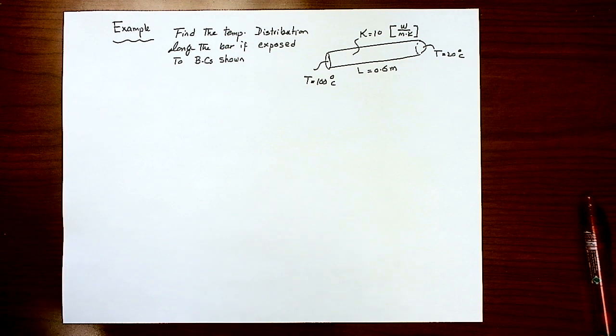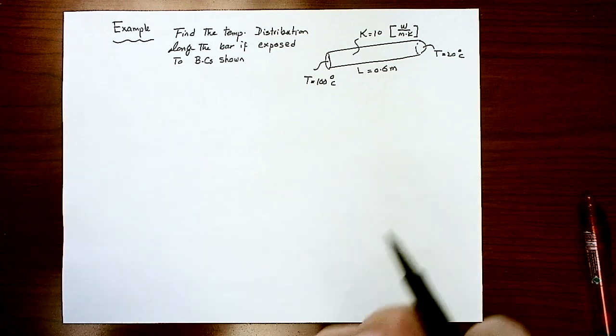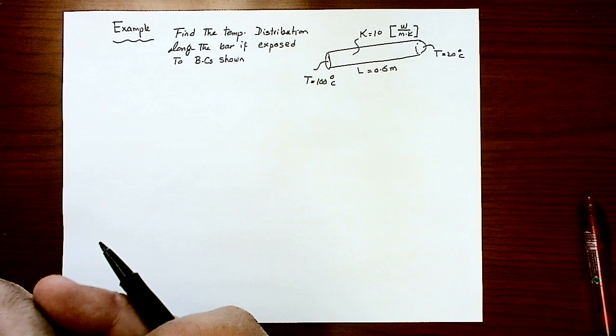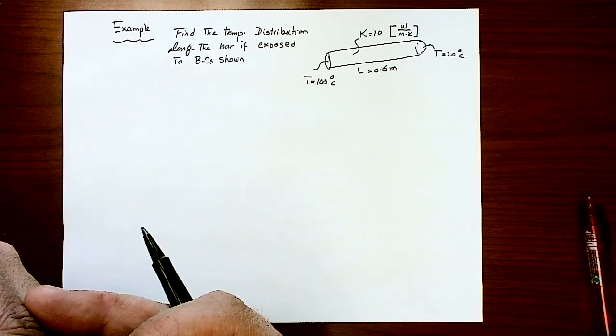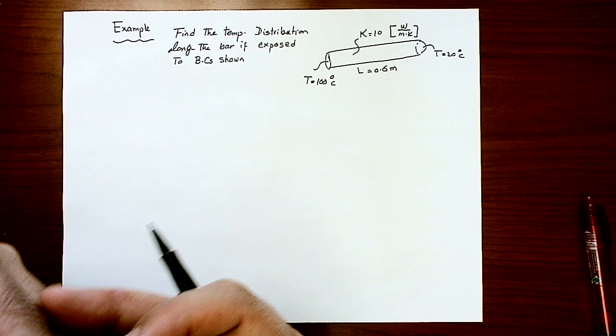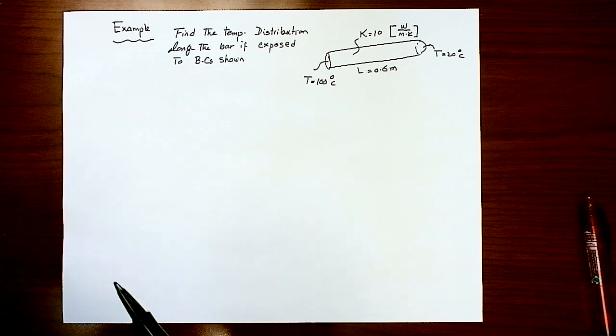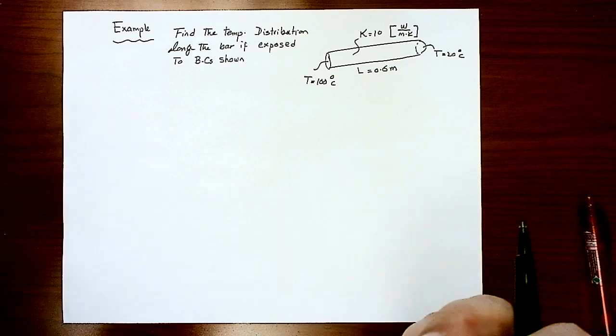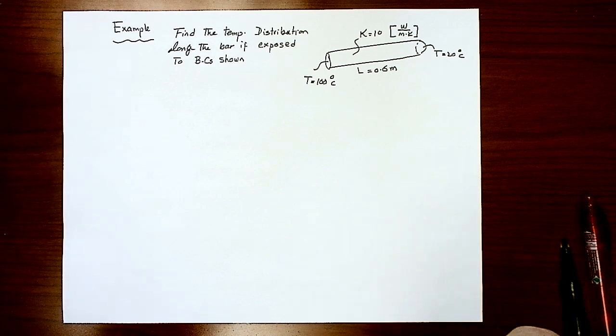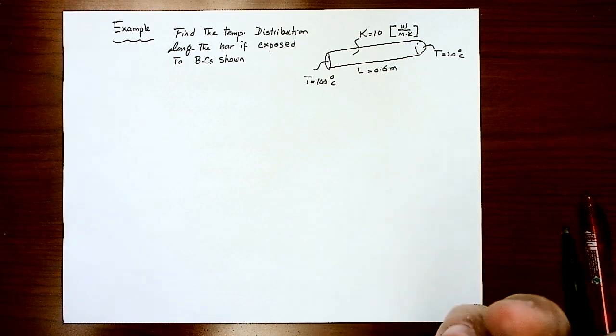To give you the sensation of the CFD approximation, I will solve that example first analytically. Then after we solve the analytical solution, we will do the approximation using the discretization method of central finite difference, and get the answer for the same problem. So this example is meant to show you the difference between the analytical solution of a problem and the approximation, and how good or bad the approximation would be in a simple problem like this.